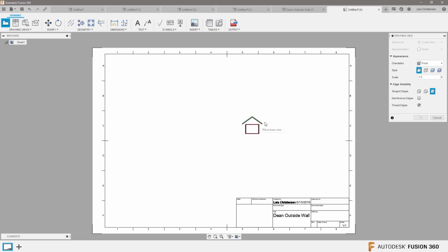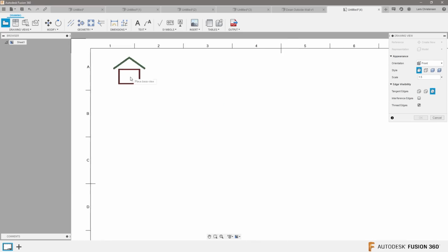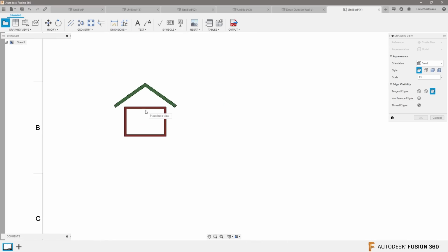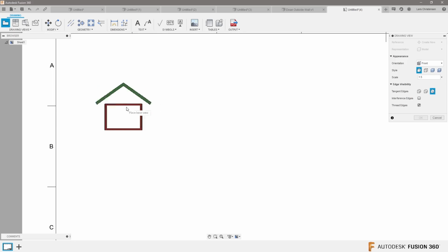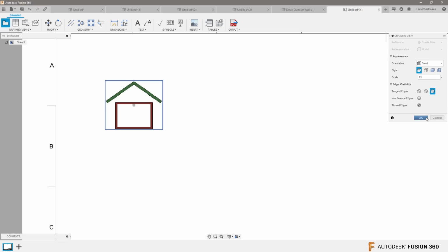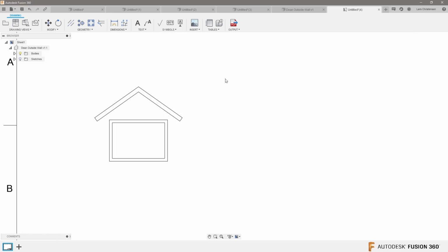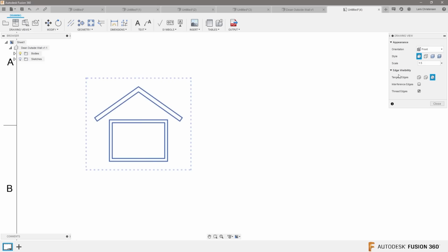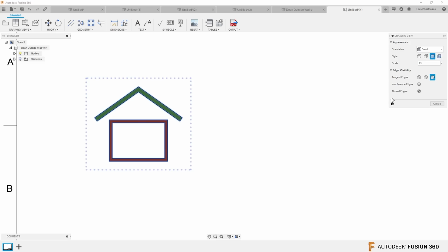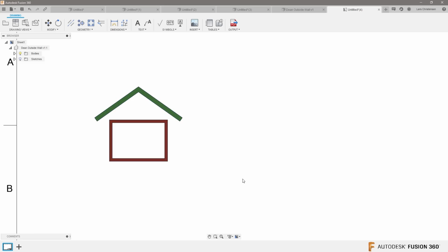And of course, you have to set your drawing templates and all. There are videos on that. But you will see here that one way to do this is just to go in and place this view like this, and you might say that is exactly what you want. Now, if I just hit OK, it would turn just white and black because 2D drawings primarily look like that. But if I double click on the view again, the menu comes up. You can turn the shading on right here, and it will bring in the shading from Fusion.